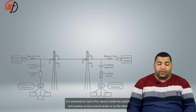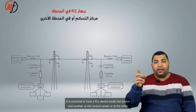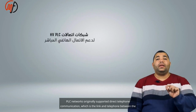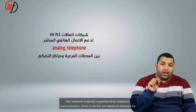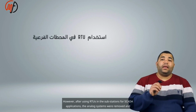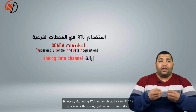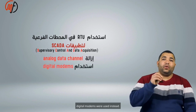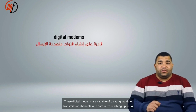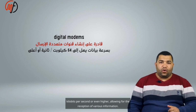It is essential to have a PLC device inside the station and another at the control center or at the other station. PLC networks originally supported direct telephone communication, which is the link and telephone between the substations and control centers. However, after using RTUs in the substations for SCADA applications, analog systems were removed and digital modems were used instead. These digital modems are capable of creating multiple transmission channels with data rates reaching up to 64 kilobits per second or even higher.